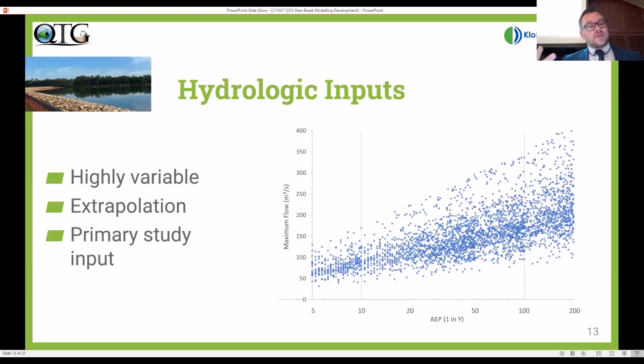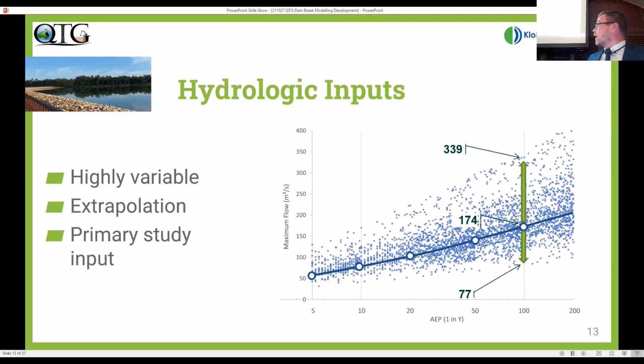What I'm trying to show is that if you've got a really good hydrologist or flood engineer on your project, and they have good data and do a really good job, then you should end up with flood estimates that follow that curve. However, as the scatter of the plot indicates, your design value might vary by plus or minus 50% relative to just this example. And if we look at the probability, we're only at about 1 in 100. So you can imagine the growth in those confidence limits associated with a PMP or your more extreme events moving off to the right.